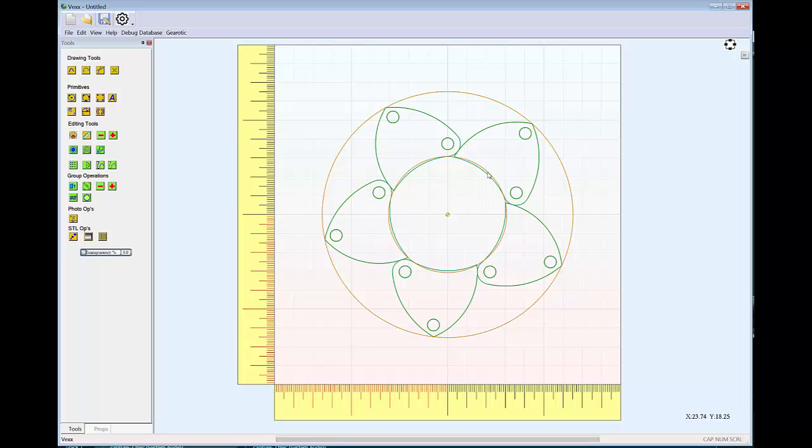But we need to see how this control ring does its movement, and we need to have a slot in it to control these vanes with the proper amount of rotation. Now, how much rotation it takes to close the vanes is really a design consideration for you at this point. The less you need to turn the ring in order to open or close these vanes, the more power it's going to take to close the ring.